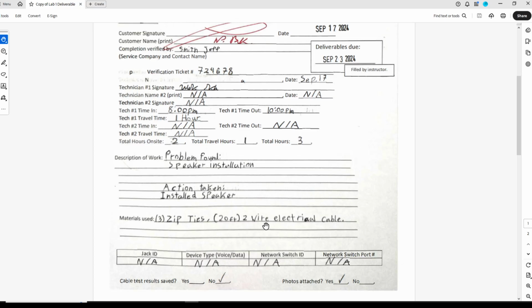I would call that person and ask, what wire was it? What wire did you use? Look at the box of the wire. Look at the reel. There should be a sticker on it, and usually it's an 18-2 FT4 stranded wire. Or sometimes there's actually a specific model number on that, if you use that with your company.